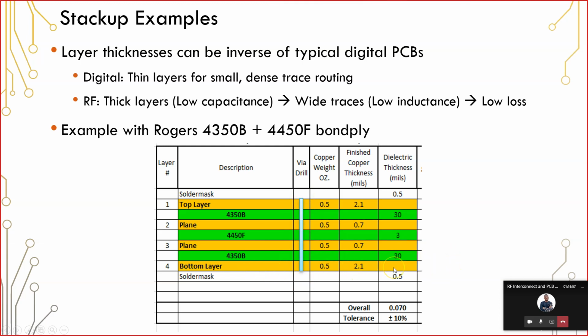However, on the bottom layer, and as we'll see later when designing transmission lines, you have to have some ground pour in order to set the transmission line impedance to 50 ohms for any high-speed signals. That can be challenging because if I fill this bottom layer with copper pour, it creates an unbalanced stack-up. And some fabrication houses will complain that having copper pour on the bottom layer, but no copper pour on the top layer, is possibly going to warp the board.